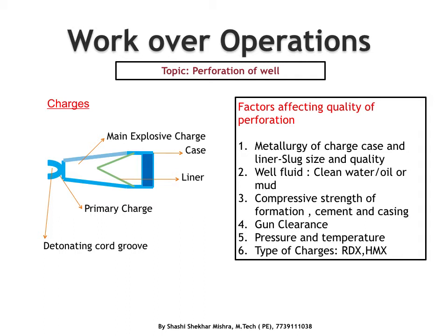Then also the pressure and temperature have an influence on the perforation. If there is a higher temperature, then we have to go with different charges that are designed for higher temperature, and the charges for higher temperature provide less penetration. They also have less sensitivity, which increases the chance of misfire.